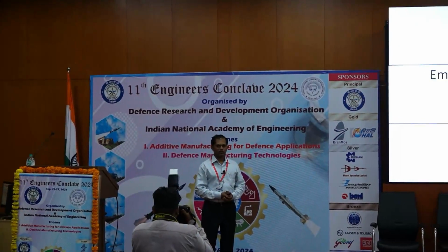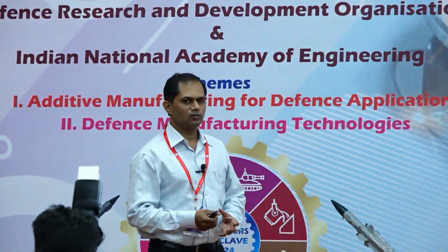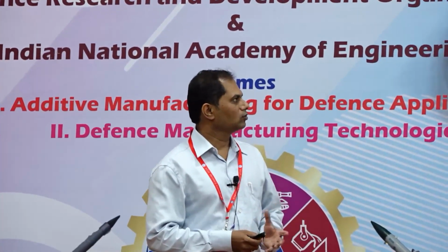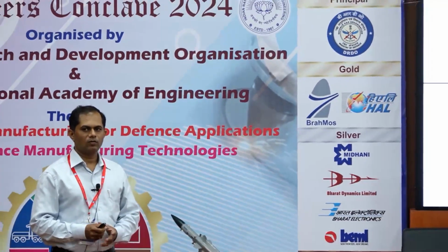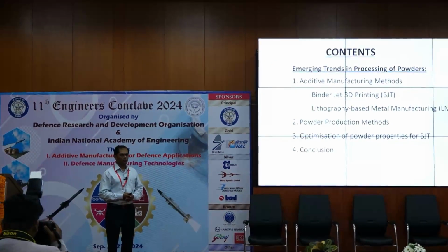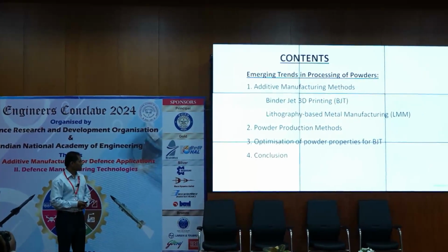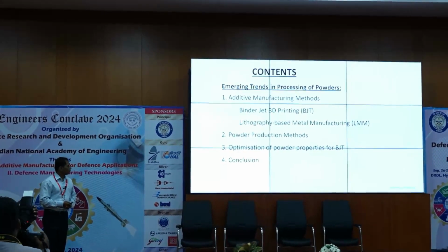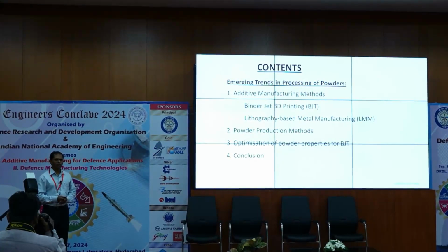I would like to thank the organizing committee for giving opportunity to industrial partners like Indomet, because most of the lectures are from research academics. And so I would like to explain here about the emerging trends in powder processing. Most of them have already talked about laser powder bed fusion or EPM, or we can say beam-based additive manufacturing. So today I would like to talk about sinter-based additive manufacturing, especially binder jet 3D printing and lithography-based manufacturing, which is relevant. And a little bit on the powder production methods, what is happening, and how we are working at Indomet on optimizing the powders for binder jet 3D printing.